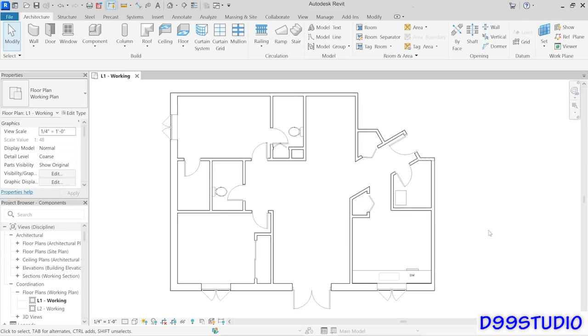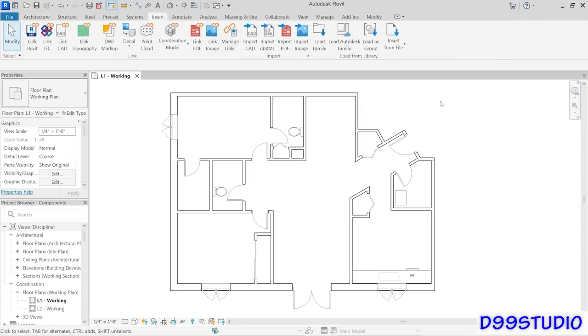If you haven't installed the library and you don't want to do the download and install, I've provided copies of each of the families that I'm talking about here in this video with the exercise files. They're in a folder called OTB, so you can load them from that location, and that would simulate the same thing. What about the other option that it said there? It said we could use Load Autodesk Family. So I'm going to go to Insert, and we've actually looked at this tool in an earlier video, but let's look at it again.